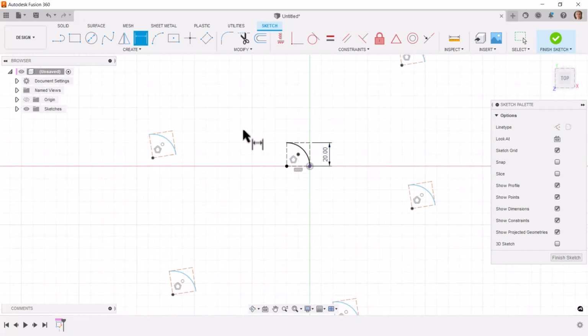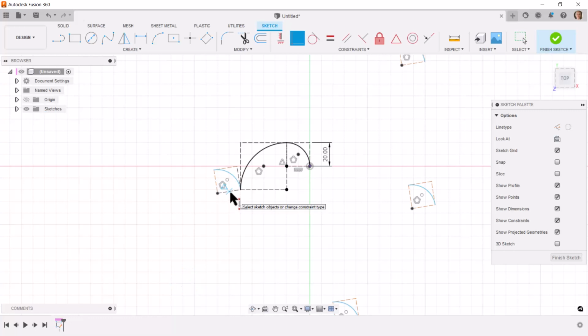The dimension doesn't matter, but don't change it drastically at this point. We'll change it later. I'm then going to do a coincident, and I'm going to select this arc and put it at the end of this arc, and then I'll hold down the Shift key, and I can get the midpoint of this line, and I'll put it at the end point of that line. Now this line will always be twice the length of the previous square. Then I'll keep on doing that, so I'll do coincident from here to here. Now sometimes when you try to do the midpoint, it can't solve it, and that time it didn't solve it, so I'll help it out.